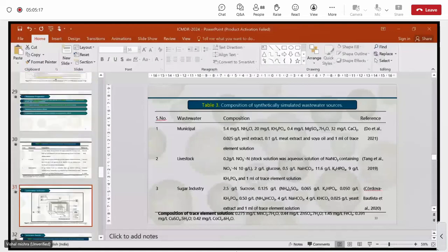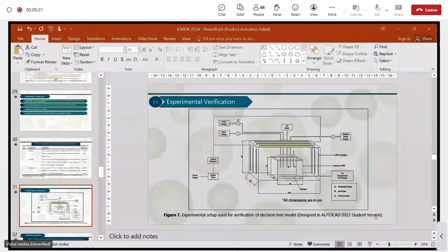So these are the photobioreactor systems which were actually used. This is the 3D drawing of that. This shows how we maintain the power supply and how we maintain the time. There was an electric regulator. We supplied acid and base to maintain the desired pH values for the macroalgae. Then an air compressor system was there. We supplied CO2 to them continuously for growth. Then a peristaltic pump, pH probe, and thermometers were used to control the flow rate, the pH of the entire medium, and the temperature of the entire box.